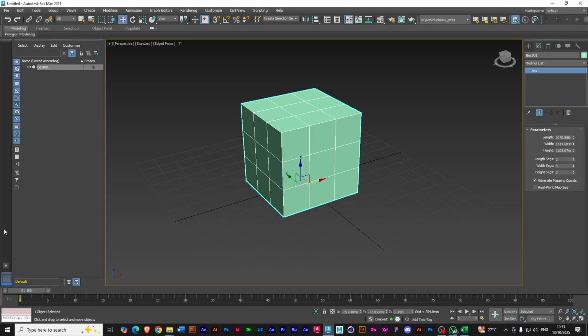It will be this way. Good. And my X will be this way. So that means we are now introducing a new axis, pointing up towards me. That's why we have the Z going up and the Y going that way. Because in plotting, this is your Y, based on how I'm looking at this. So that Cartesian axis follows that paper and plane. And then you can do your user coordinate system and change it if you like.